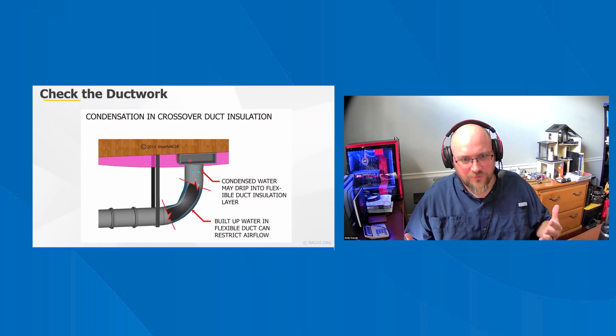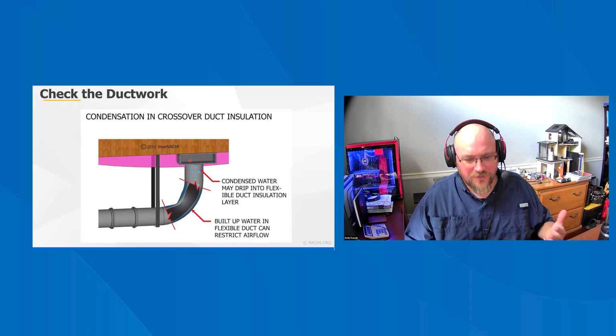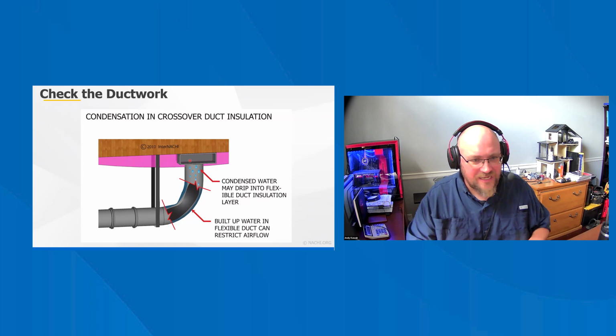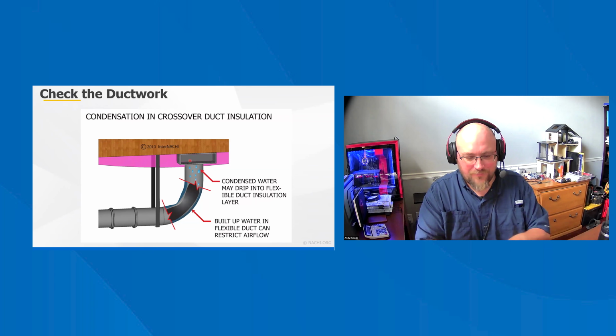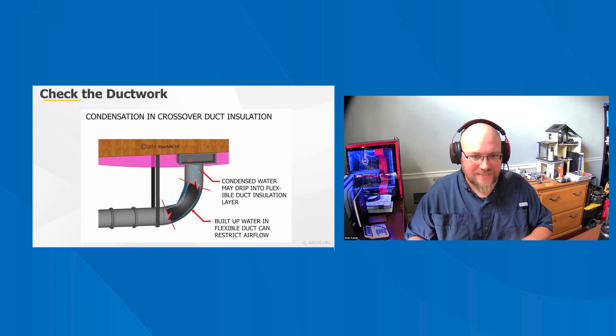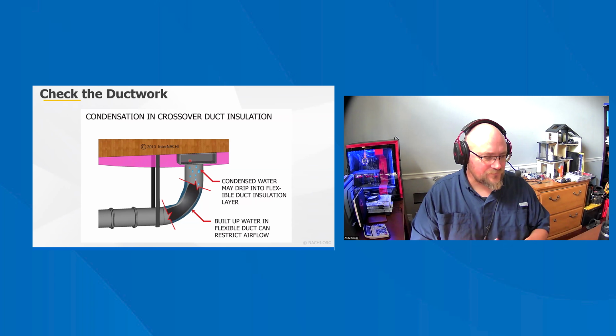In Arkansas, that's super important, because otherwise you get that humid air, and our vapor retarders are not installed correctly here. They don't overlap, they don't tape any of that. They basically just put them down and butt them up together, so it's really easy to move them and then have exposed dirt.